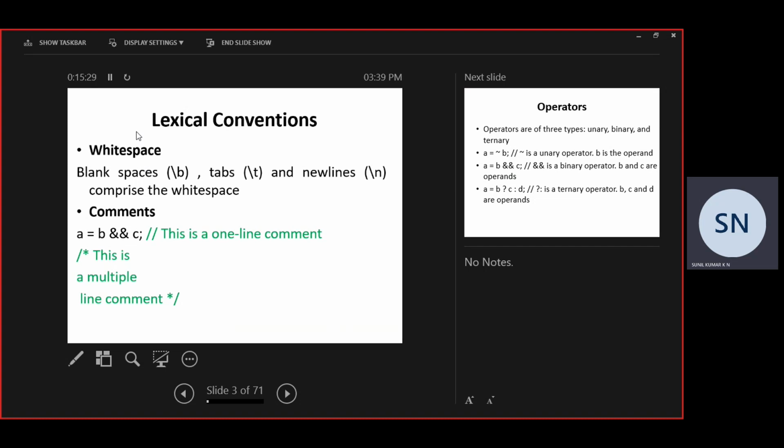end module there will be nothing there, right? So between the module and end module, empty space has been given, or whenever there is a semicolon, if you put a semicolon, then the very next line, from this line to this line, empty white space will be there. So empty space or white space, if this occurs during the execution of a simulator, and it comes across white space, it will be treated as the next line.